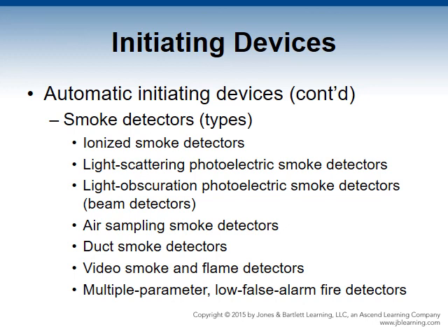Another system: duct smoke detectors are used to shut down commercial air distribution systems that can move large amounts of air throughout a building in a short period of time, spreading the smoke and toxic gases all over. Duct system detectors are not early warning detectors. Some are mounted inside the ductwork, while others are outside and attached to air sampling tubes in the ductwork.